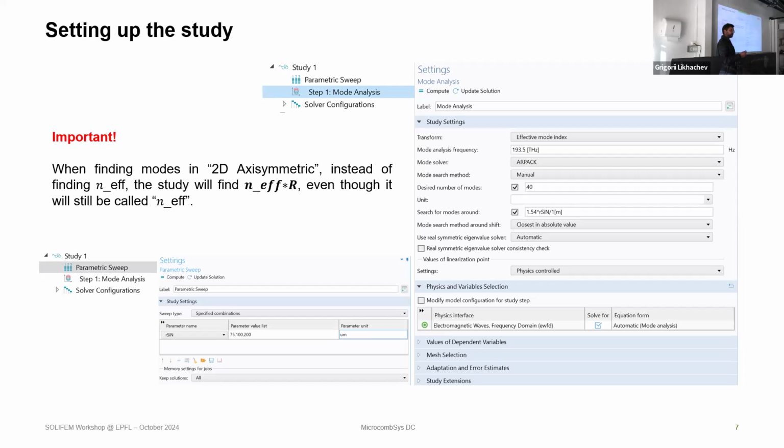It makes sense that the largest effective refractive index will be the solution, because you can imagine the whole mode is inside the silicon nitride, so the effective refractive index is largest. But still, I think there could be other modes which have nearby the same refractive index. If it's too thin a waveguide, everything is oxide. So then what will you do?